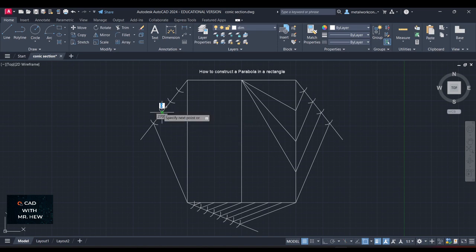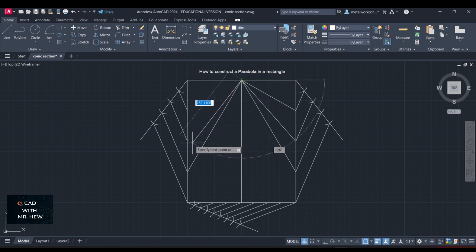All right, so we have divided the line, right? So if you had used a T-square, it is the same procedure that you did on the left, okay? All right, so the next step, we're gonna draw a line from this point, which is where the middle line intersects the top line on the rectangle, to here. So these are straight lines. Hope you're following so far. Good. Gonna join those. Enter. Gonna join those. Enter. All right.